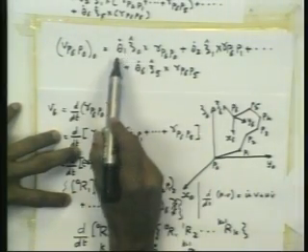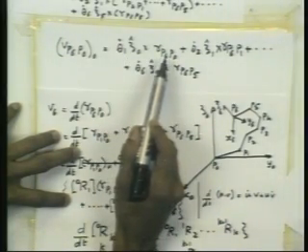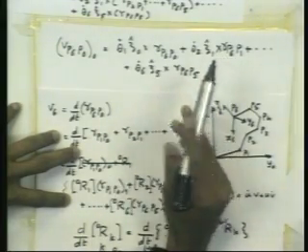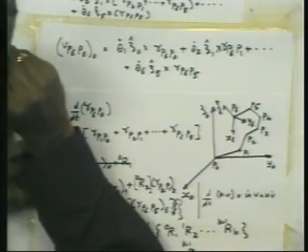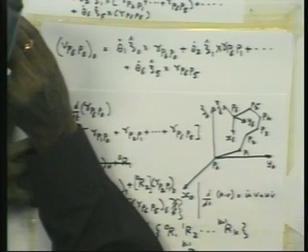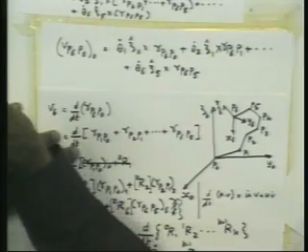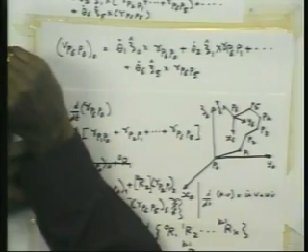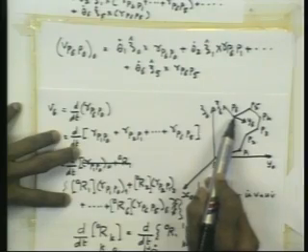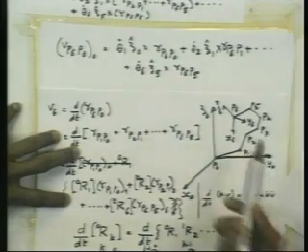So this term arises like that. What about this term? Hold all the joints except the second joint fixed and move the second joint with velocity theta 2 dot, with the rest fixed. The linear velocity imparted to this particular point through that exercise is this term.